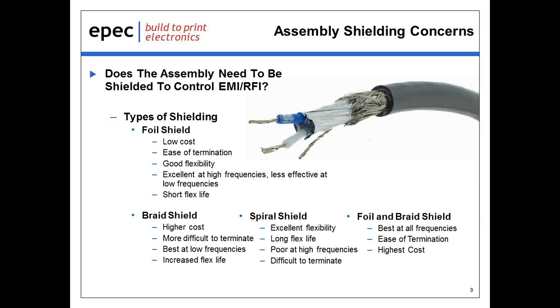The foil tape is applied around the components that are to be shielded or isolated. The foil tape exhibits some pretty good flexibility and is the easiest of the shields to terminate, but it is not recommended for applications with an expected high flex life. Foil shield does offer effective results at high frequencies, but isn't as effective if the signal is going to be transmitted at a low frequency.